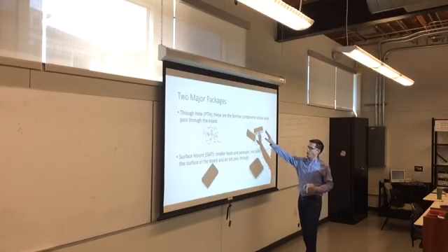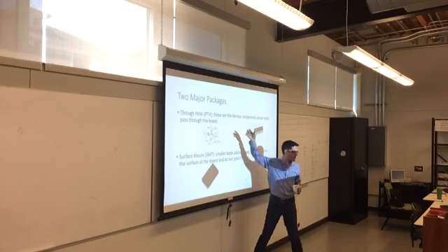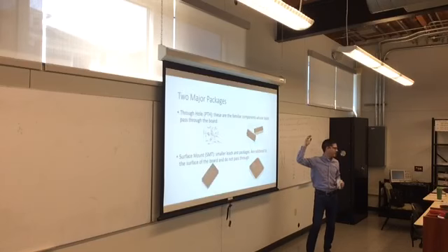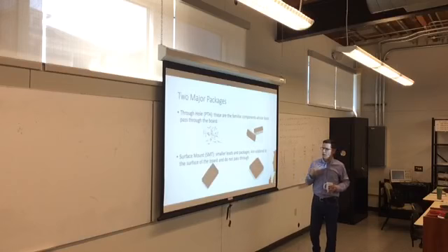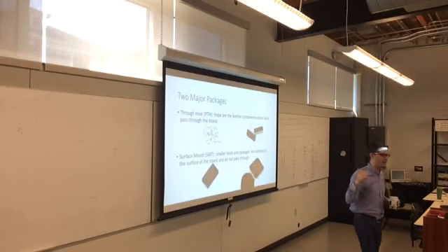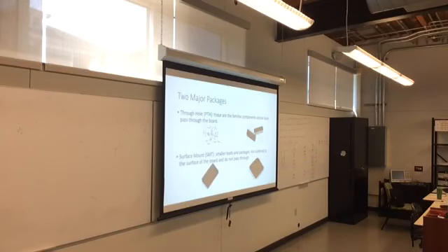So when I say through-hole, I'm talking about your classic resistors, your classic ICs, things that you can snap into a breadboard. Through-holes are really easy to use. It's what you're familiar with. But I'll be honest with you that if you make a design with that, you're actually going to have a worse time. It really is a worse time to use through-hole components because it's gotten to the point where the surface mount stuff can be pretty easy to just solder and paste on.